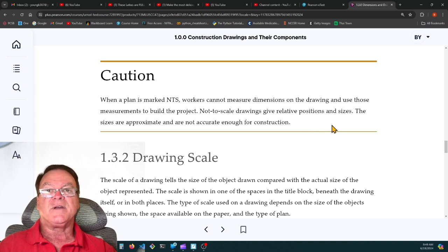A lot of times on the drawing they'll put NTS and field verify. So they're saying there's a beam and we want to put a light exactly 12 inches to center off of the edge of that beam. And then they say field verify. Verify where that beam is, verify where that fixture is going to go. And if they drew it, they didn't draw it that accurately, they just say not to scale.